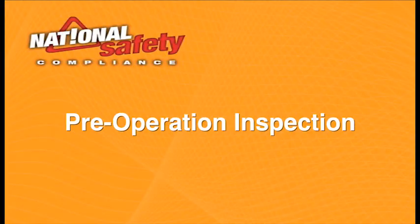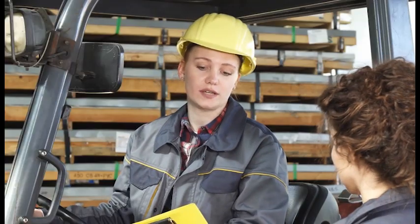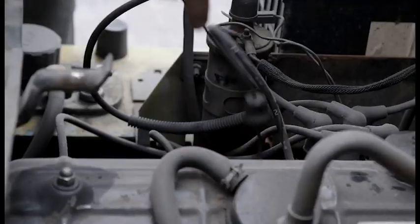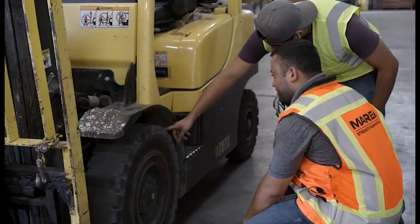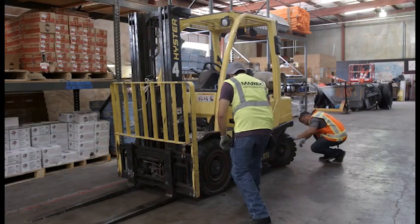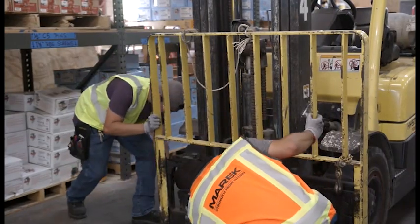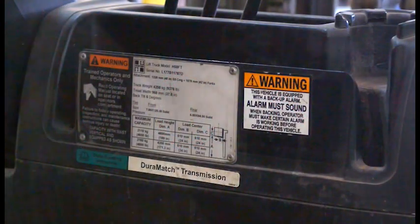Pre-operation inspection. Before starting the forklift, conduct a pre-operation inspection which covers, but is not limited to, the following: fluid levels, oil, water, and hydraulic fluid; leaks, cracks, or any other visible defects; tire condition and pressure, including cuts and gouges; condition of forks, load backrest extension, finger guards, safety decals and nameplates.